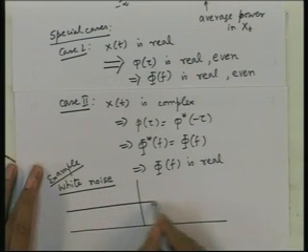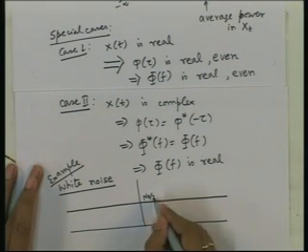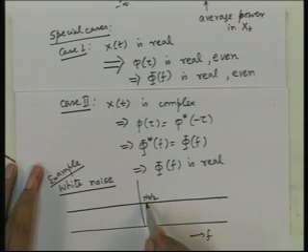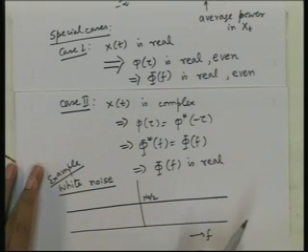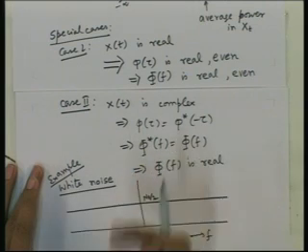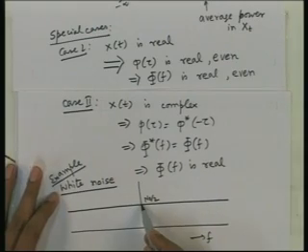In the two sided picture, the density is usually denoted by n naught by 2, where n naught is the one sided density, because if you add the density at minus frequency and plus frequency, you get n naught. So, this is n naught by 2, the two sided density function amplitude.